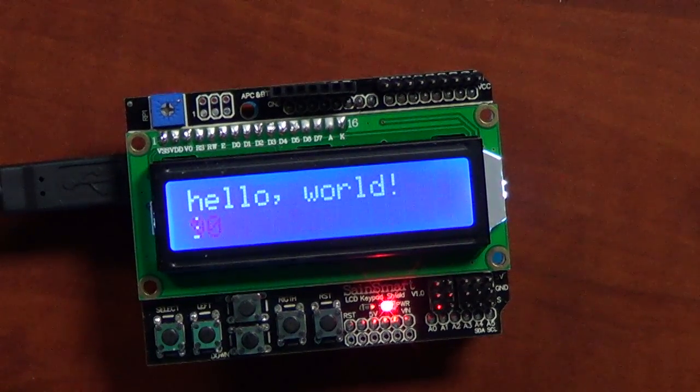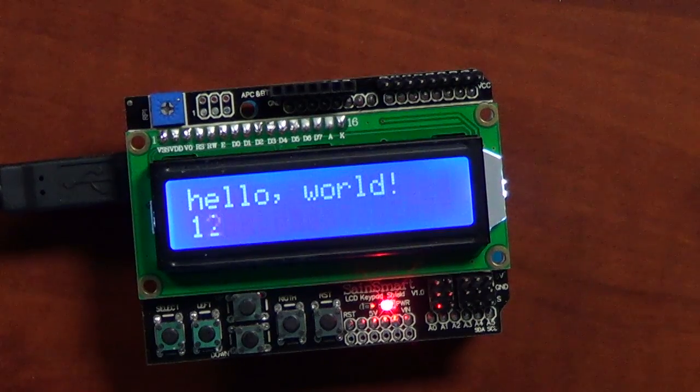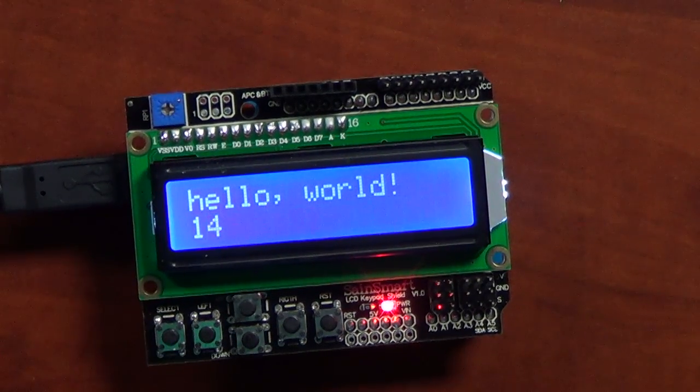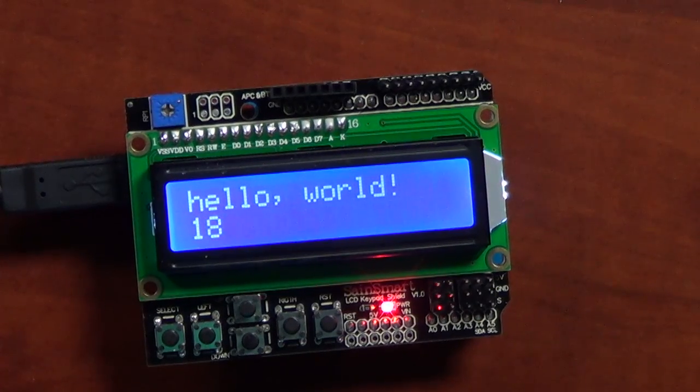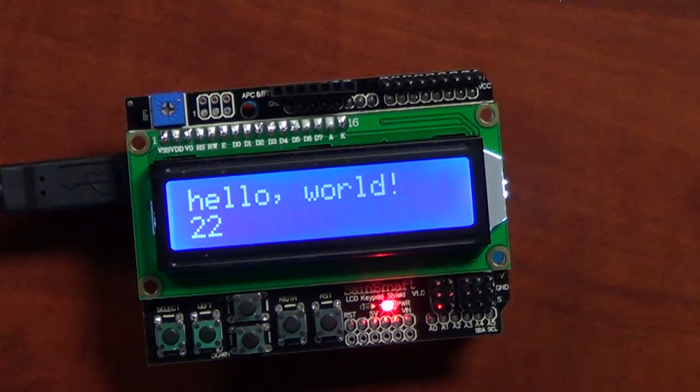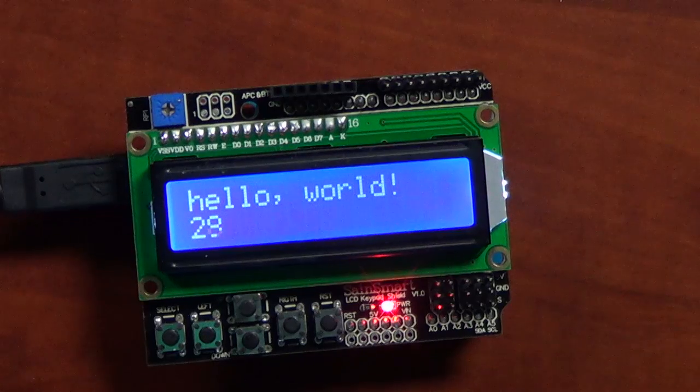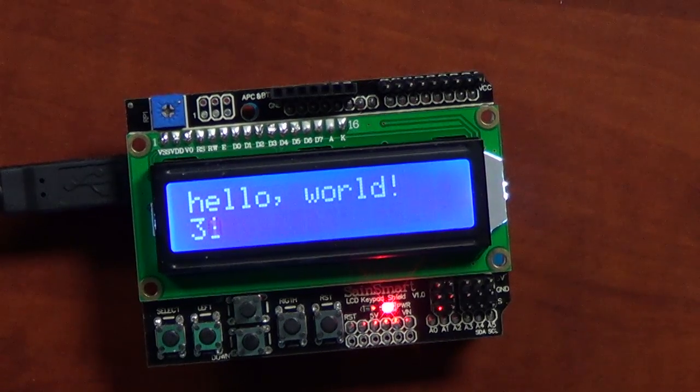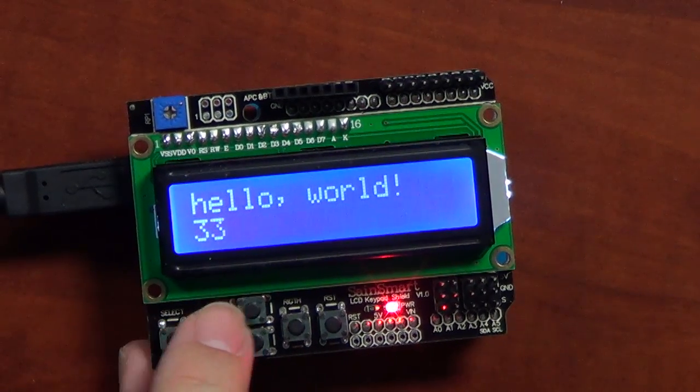Like I said, the only concern is the number of pins that it's using to display. It looks like it's using 8 data pins connected, and then the 3. So it's using all 11 pins. In the case of this Arduino, I've used up all of the pins that are available, and one of the analog inputs I've used up as well. And that one input is used by these buttons to display values.